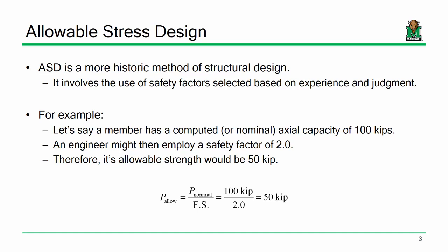Now, I'm a table salesman, and I'm going to sell this to a number of consumers who are going to put this in classrooms and offices all over the world. Do I want to tell these consumers that this table can withstand 800 pounds? Probably not. Probably what I would do is say, let's put on the package that this table has a maximum capacity of 400 pounds, okay? So that way, there's a little bit of a factor of safety built into it, okay?